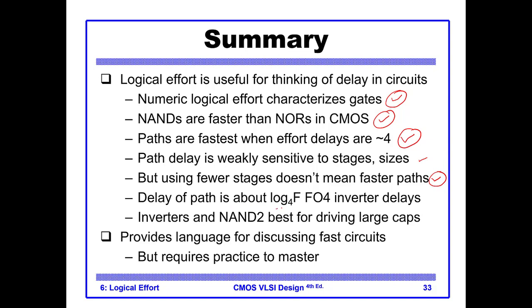Delay of a path is about log 4 of F. FO4 means fan-out-of-4 inverter delays. So it is also used to measure delay.